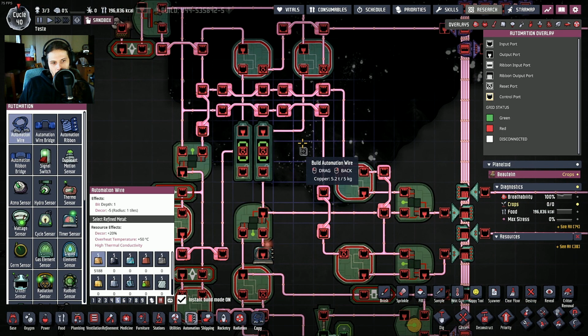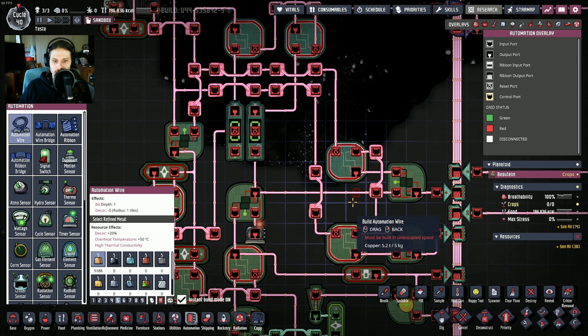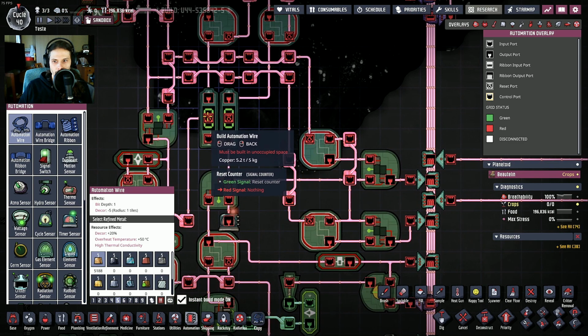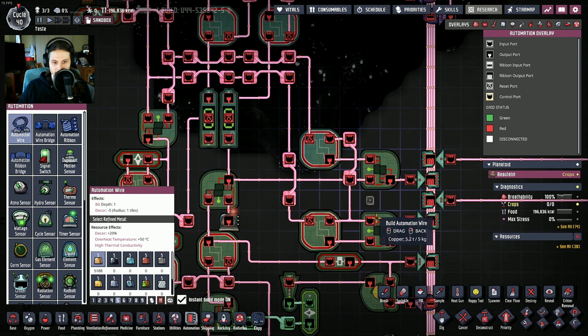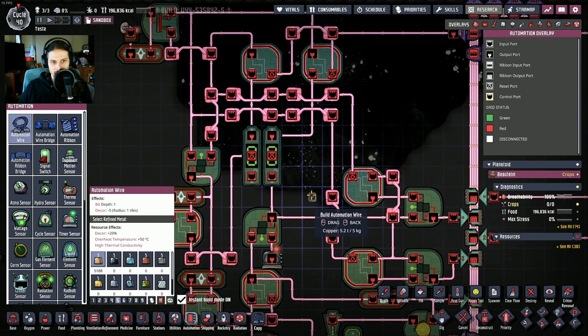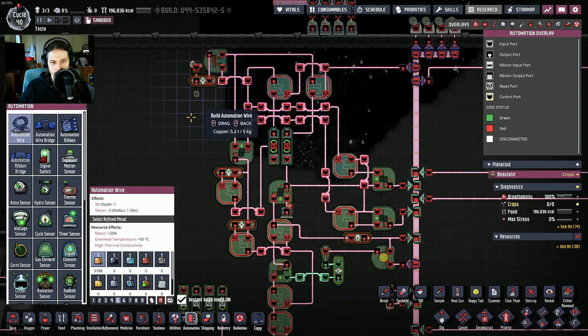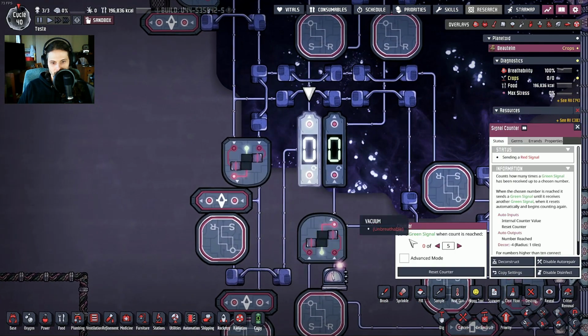Right? Okay, now things get a bit complicated, my friends, because you see, we need a way to stop the frequency from writing into the specific bit whenever the number of signals, of pulses, has been sent. That's why we have these AND gates with these memory toggles over here, because in essence, this thing over here controls the turn on and off of the entire encoder and the closing and opening of the gates for bit 1 and bit 2.